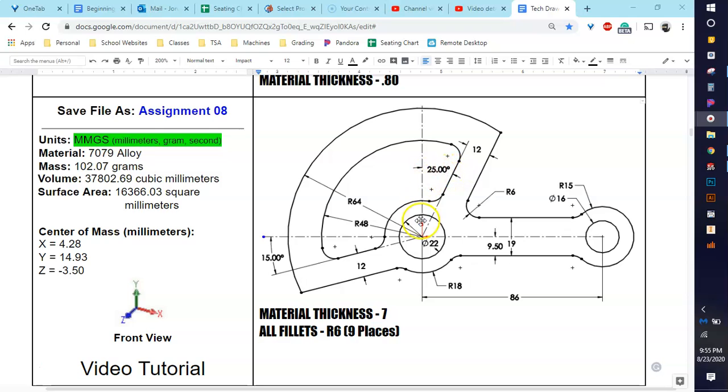And then you can actually see there's some construction lines. So construction line here, construction line there. So what this construction line tells me is that this line itself and this line itself, if they were to continue, would go right back to my origin. So meaning they are coincident with my origin. So these construction lines just kind of show me meaning. They don't necessarily need to be there, but they show me some meaning.